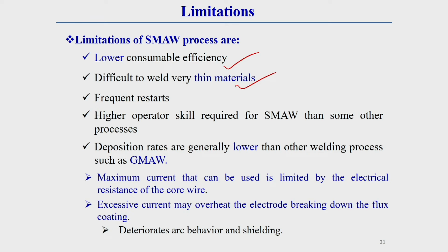Generally what happens, during starting of the arc itself, there is a chance of melt through of that thin material. That is why it is difficult to weld very thin material, because there can be melt through of that thing. This is a drawback of this welding process. Another thing, here stick is used, so very frequent restart will be there. If the welding length is higher, then very frequent restarts are also there.